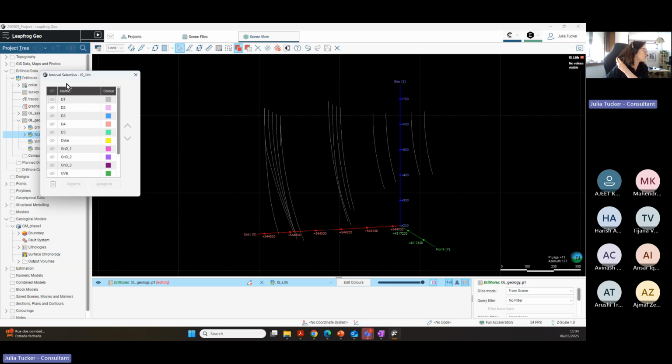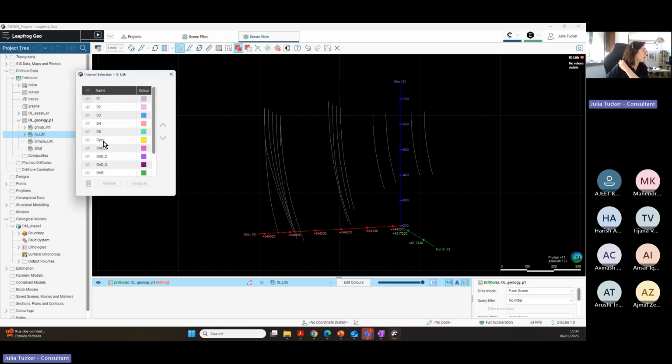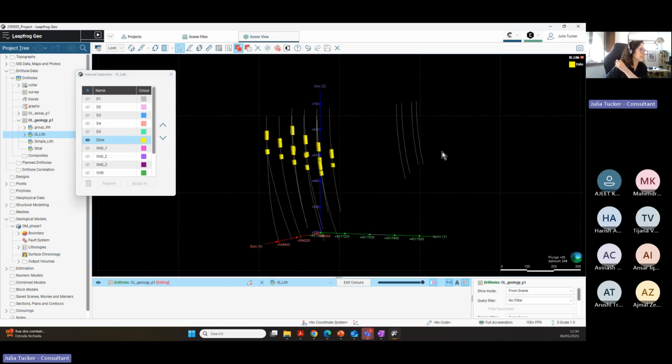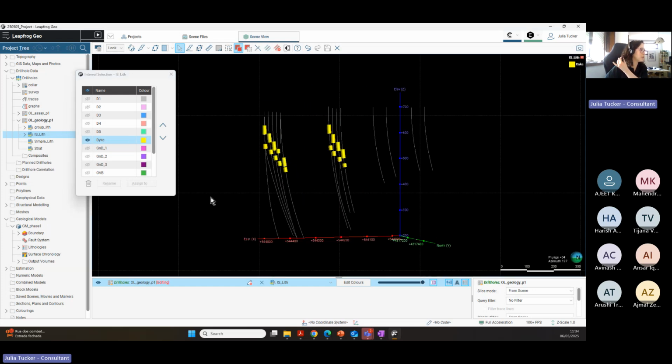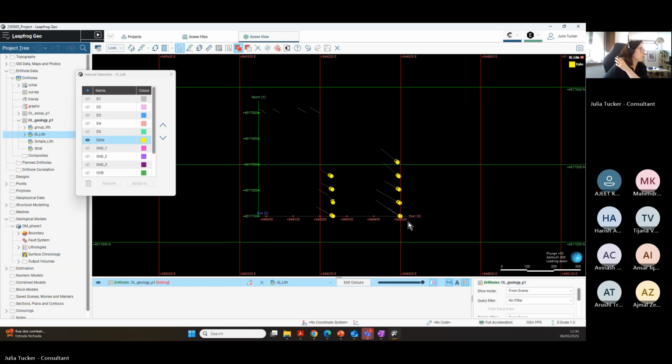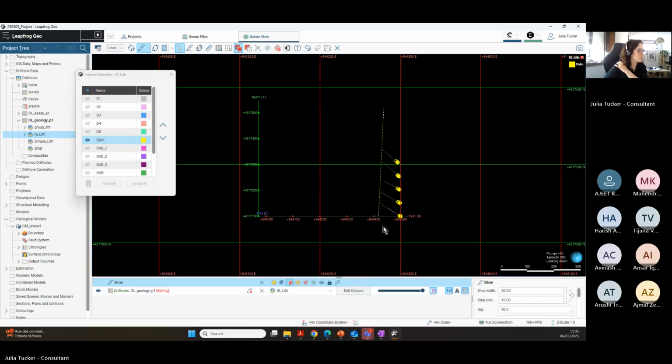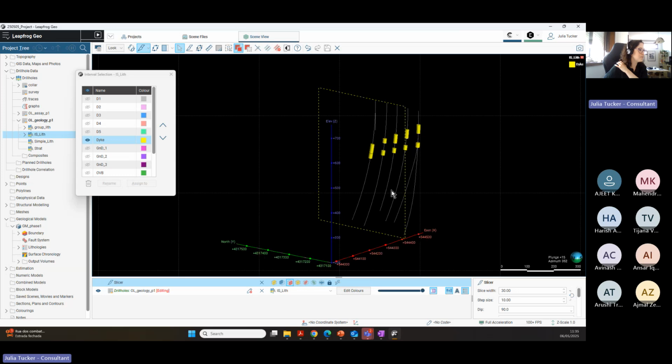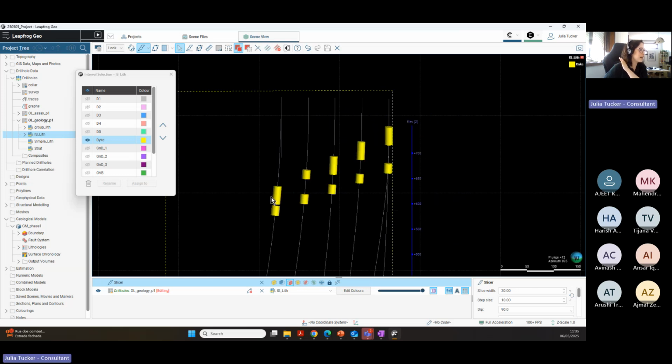So what we are trying to do here is just to select what we want. So to do that, let's just visualize what we want. And we are going to visualize just the dike. So we have here the dike. And what we are going to do now, just pressing D, we will be able also to make a slice. So I had pressed D and now I am drawing a slice. So on my slice right here, I can see exactly what I wanted to select.